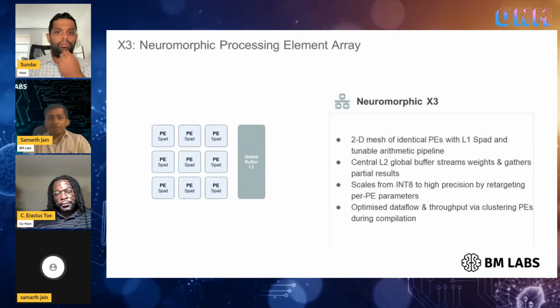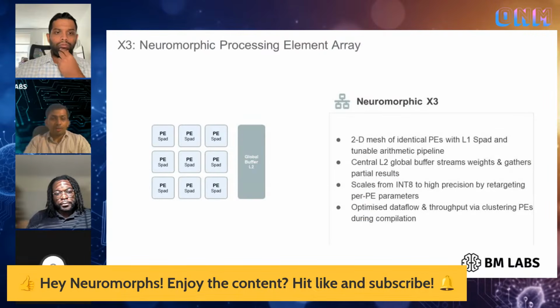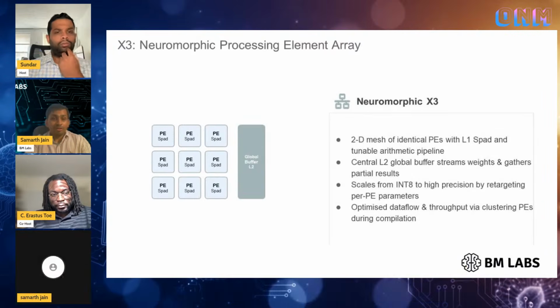Yeah. So as I was talking about, Aristus asked what is in-memory compute and how does it benefit? It is benefiting because we are trying to cut down the access time to L1 and L2 at least, right? We can match the density of L1 already, and we're trying to match the density of L2. So you don't kind of need these memories, it's already there in your core. So it saves a lot of energy in transporting the data back and forth, right? Even L1s are quite complicated. They have multi ports to make them high speed. So it's very convenient to have everything inside the same memory.